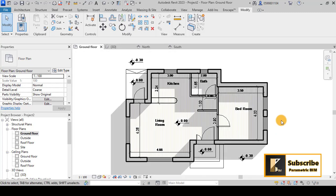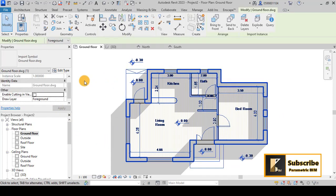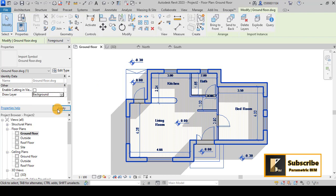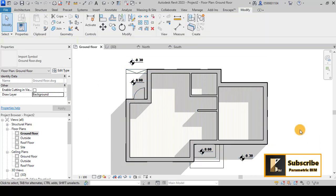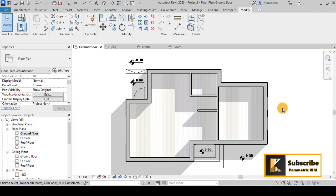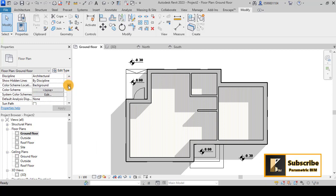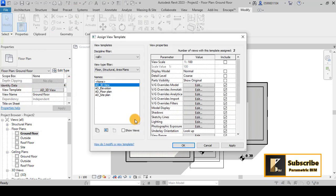But there are also other approaches for this. Maybe, if you don't know this procedure and you have background and you don't have the opportunity to make it foreground, let's suppose that you can go here to the visual style and make it a wireframe, but it is locked because I have a view template here, and I will also teach you how you can make a view template for all floor plans, for example, or elevations or site plan.